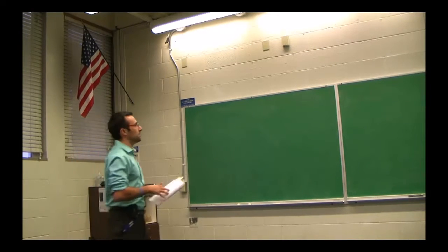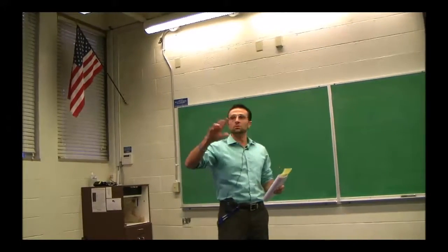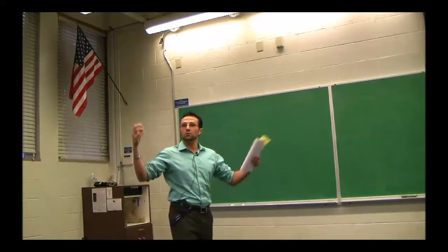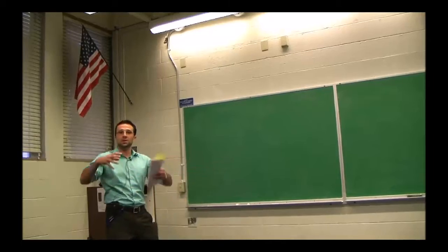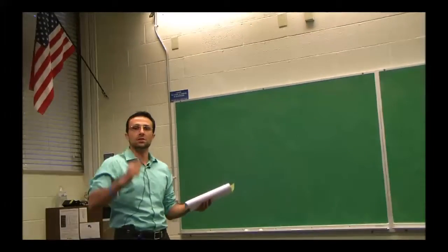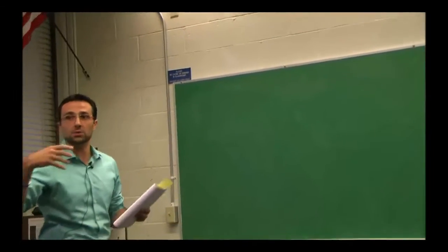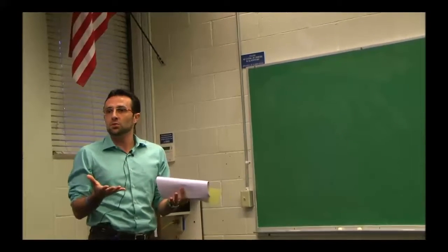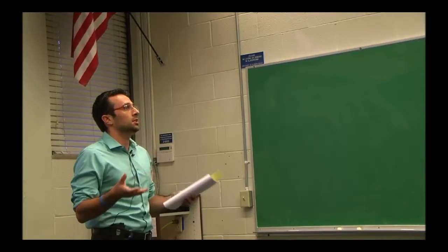So we have covered the heliocentric point of view. It's a Hohmann transfer, that's all we do. And then we disconnect from that, and we say, oh, there is a sphere of influence. I'm coming in with this velocity with respect to the planet, or I'm leaving the planet with this relative velocity. Combine the two, add them up, and get the heliocentric velocity.